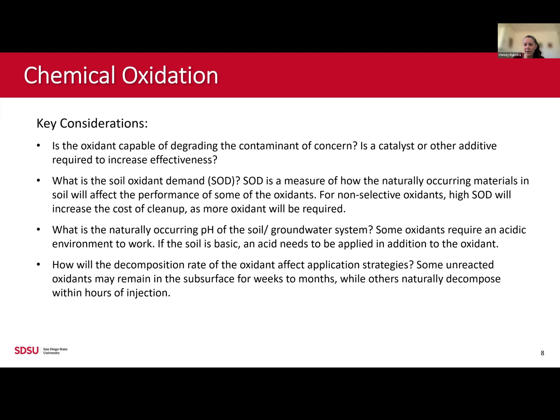So in that case, if we're going to do chemical oxidation, we may consider whether it's less expensive or easier to do ex situ and have fewer chemical costs, but now we have to do pumping and having a different tank to treat this in and so on, or whether it's easier to just put more chemical in, satisfy the soil oxidant demand, and then also satisfy the demand for the oxidant from the chemical that we're actually treating.